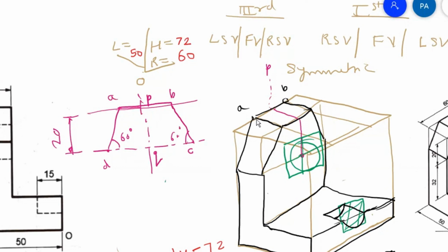Then from this point A, which is this point? This point is D here, which we had already done. So join DA. So DAB, and similarly there is point C which is not in the picture. Now this is the bottommost, behind portion. Now we have to draw at a distance of 20 mm towards the observer from behind.